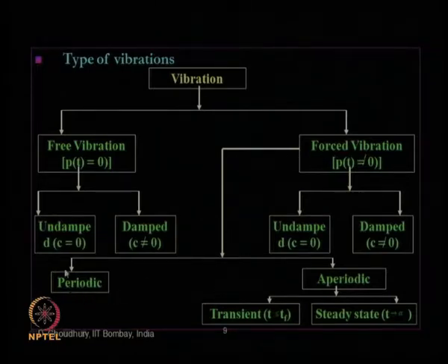What is that? Periodic is when the applied dynamic load repeats with time, whereas aperiodic is when it does not repeat with time. A periodic example is the harmonic loading, any sinusoidal or cosinusoidal loading, which can be considered periodic forced vibration. But when it is not repeating with time, that is aperiodic, we can also have two subclassifications.